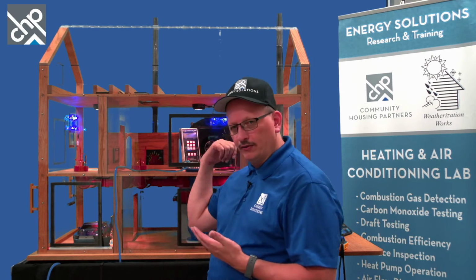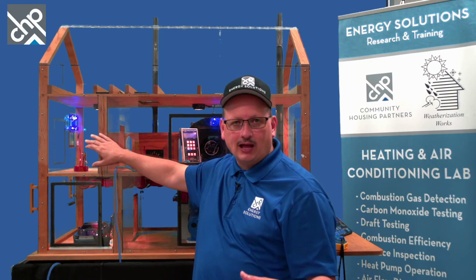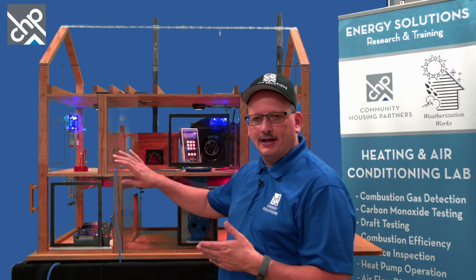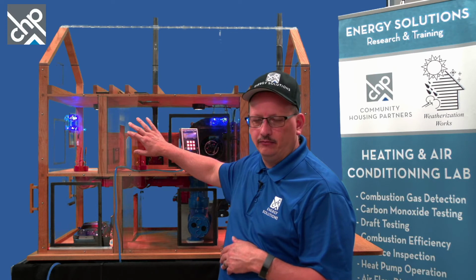Now, the rooms that just have supplies in them, like the bedroom over here, should be at positive pressure. If you smoke the bottom of the door, it should be blowing smoke towards you. But the ones that have an exhaust fan, or maybe a supply and a return in the room, the smoke could be going either way. Again, you just want to make it the worst case, where wherever your CAZ is becomes the most negative number it could be.